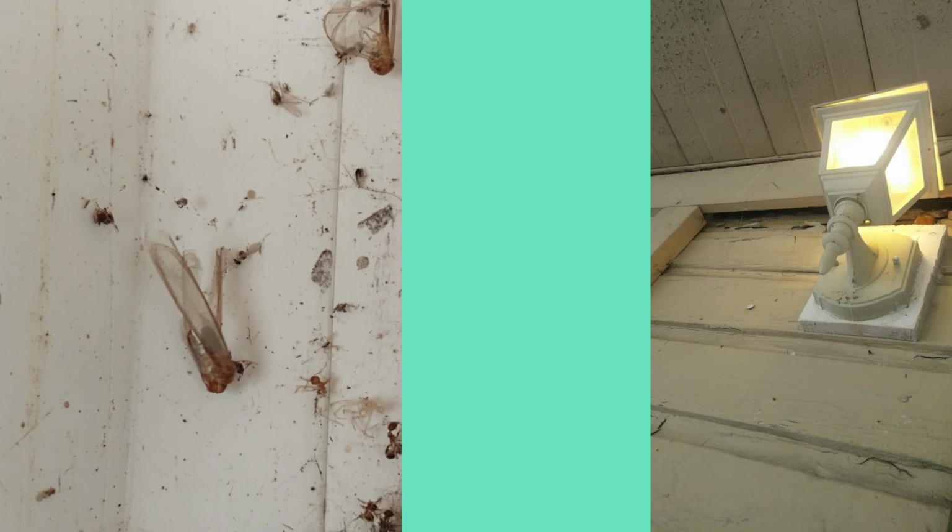But because we looked around the adjacent area, we found the swarming termite, and then we noticed some kick-out holes in the wood. So always think when you're doing your survey and inspection to look at all the adjacent areas where you think there could be termite activity.